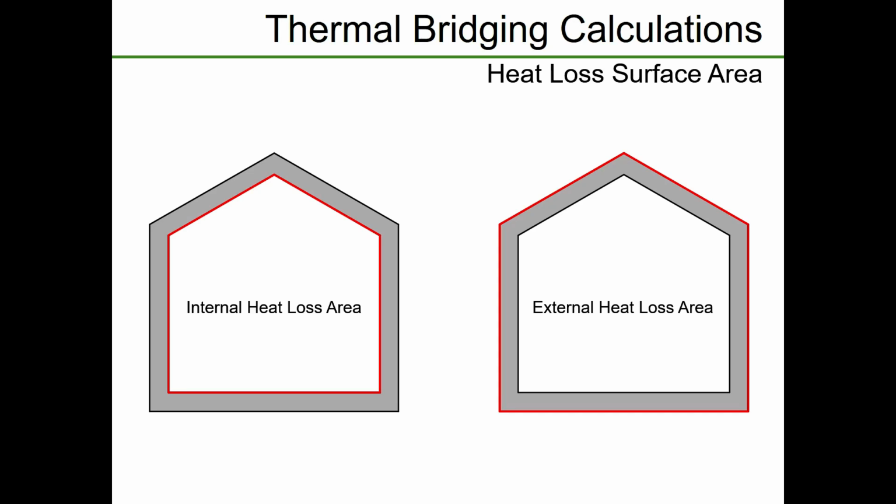So yes, you would get a different value in terms of where you're using your U values and multiplying them by the area. The areas are different, so you're going to get a different value. But then when you factor in the thermal bridging, essentially you should arrive at the same amount of heat coming out of the building. What this does is it overcompensates for the U values, so you tend to subtract the bridging, whereas here you're adding the bridging more often than not. There are cases where it might not be like that, but generally that's what happens.